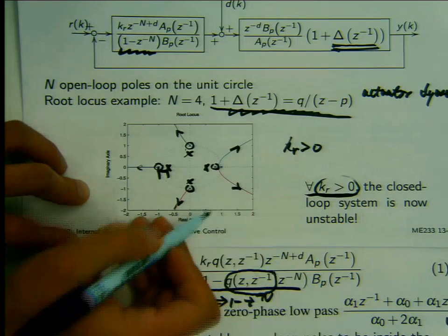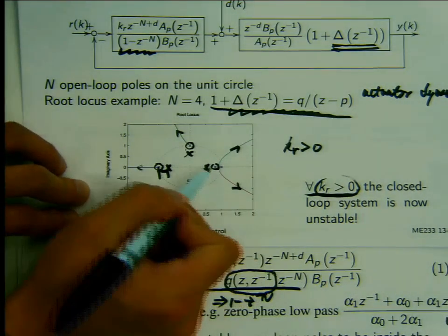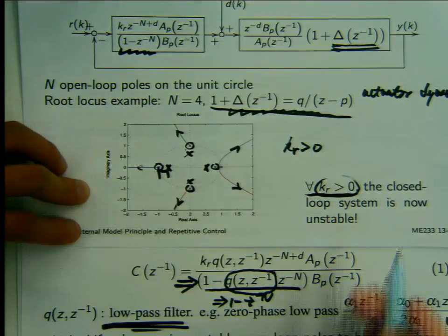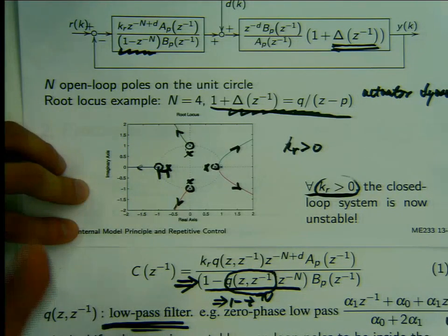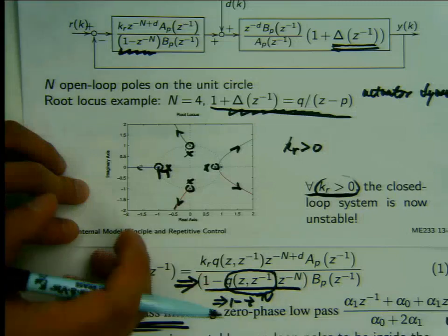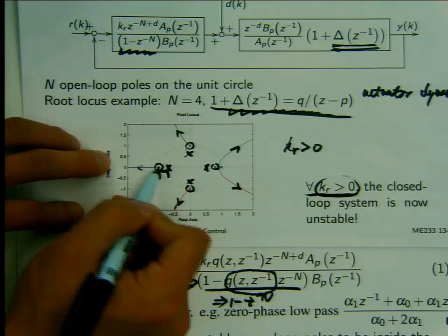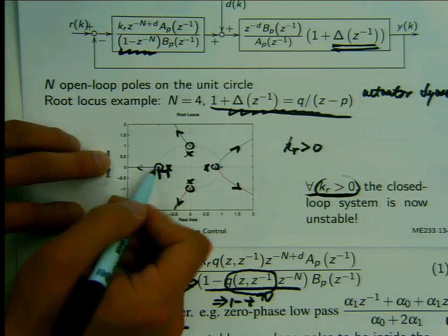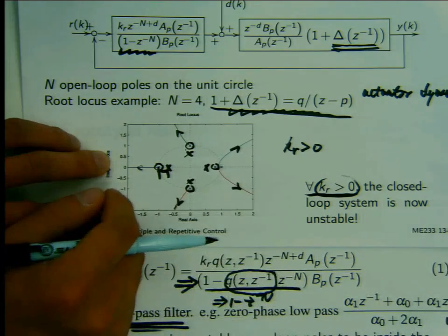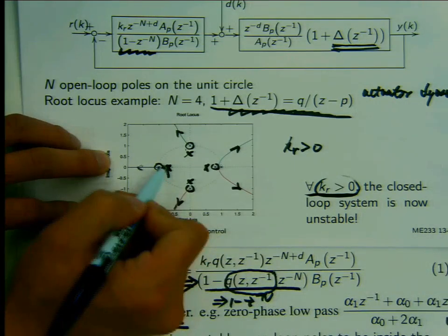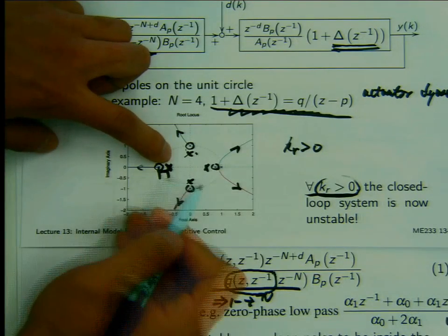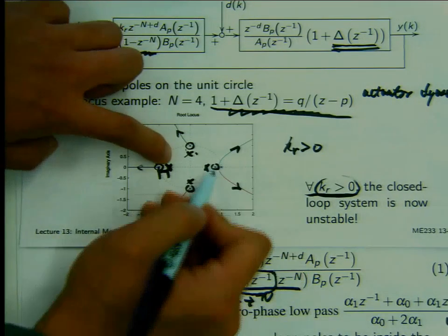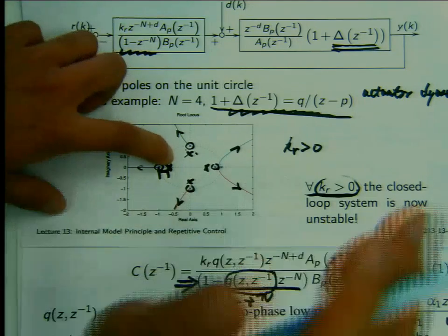Yeah, that's actually a very good point. It turns out, as we explained several lectures ago, plant uncertainties are large at high frequencies. That means at high frequencies, marginally stable poles are dangerous. So usually it's more important to shift these high frequency poles to be inside the unit circle. Low frequency poles are not that severe.